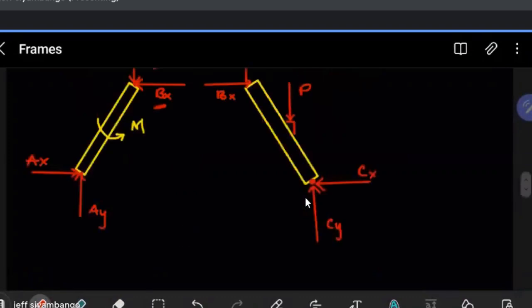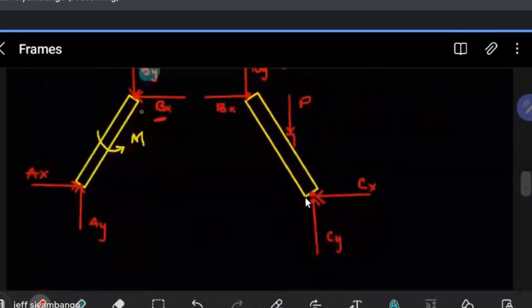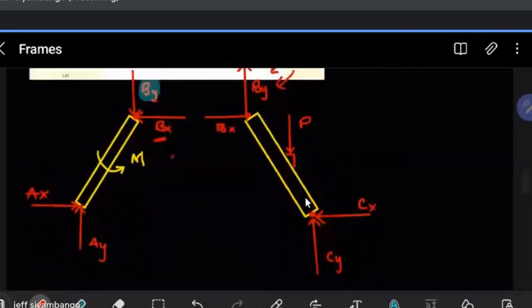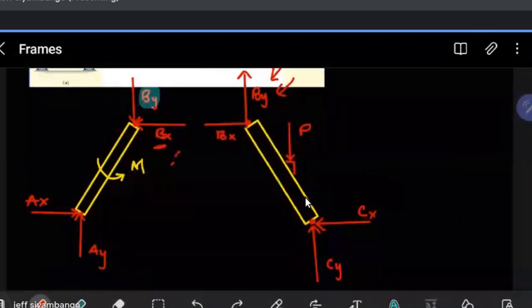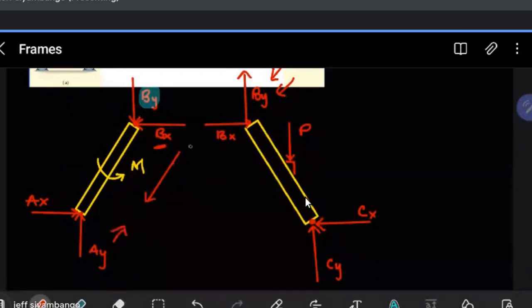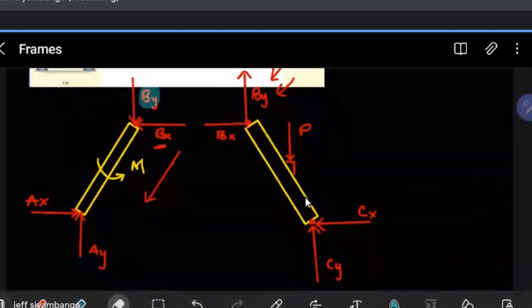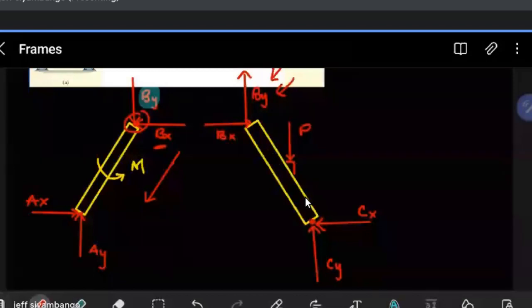The two forces: one will be a result of the member AB, and based on how we drew this one here, the force from that will be going something like this. And the force down here, of course, will be going something like this. But we're only interested in the pin here, so we'll stick to that. So this is the force acting onto the member. Now, same thing for the force here for this member, this is BC now.